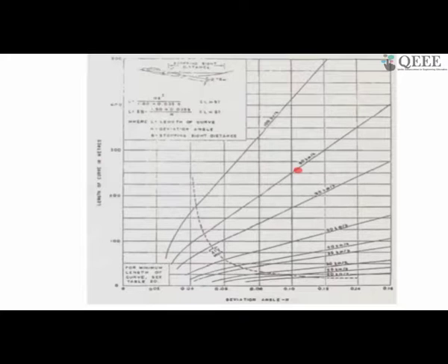So in either case there is a safety issue, and it depends on how much higher speed you are going to go. Yes, now another thing is that if you are going into the valley curve, naturally because of the downhill or descending gradient, your speed is going to keep on increasing. So if you don't check, then definitely that is where the vehicle can get into an accident.